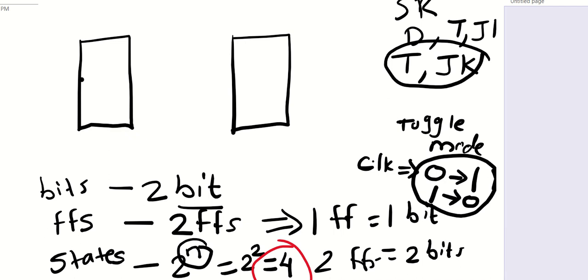And what is a counter? Counter application is actually just changing one bit. For each clock pulse, your count will either get incremented or decremented. And whenever we get a count incremented or decremented, there is only a change of 1 bit. To toggle that 1 bit, the toggle flip-flop or a JK flip-flop is used.